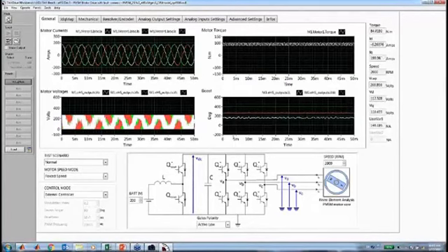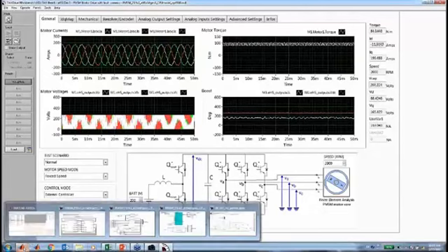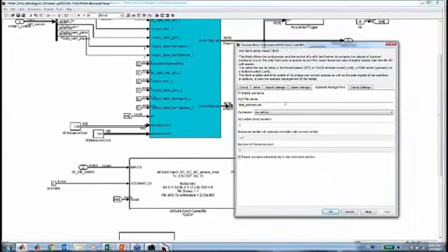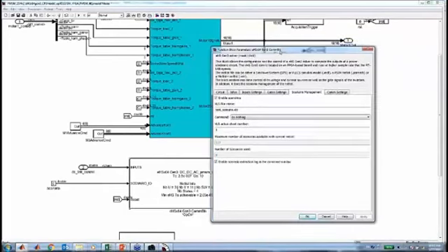So now I change the capacitor value, but I want to make changes on the fly, because sometimes you want to insert a fault, and basically inserting a fault is like inserting a resistor that's going to pass from a value of 1 megaohm to 1 milliohm instantaneously. So we made another feature called the scenario feature that allows you to insert parameter variation on the fly during the simulation. How it works is pretty easy as well.